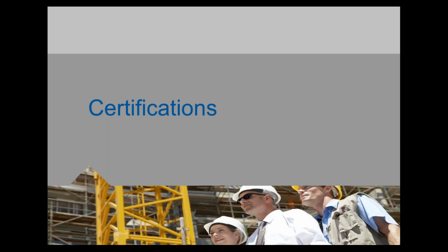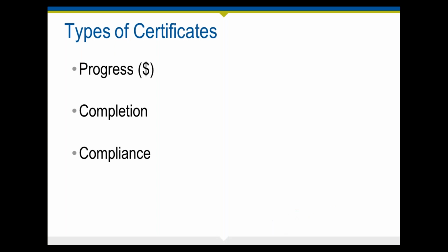So the last thing I wanted to talk about are certifications. And this is something that is often called from the design professional to provide a certificate of some sort. Typically, these are progress certificates. For example, what percentage of the work has been put in. This type of certification is used to process pay applications.